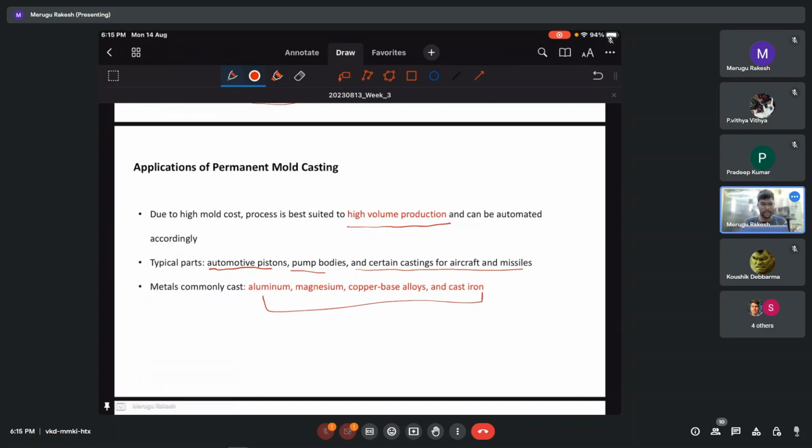So now we come to die casting. In permanent mold casting we are just making the mold, and we are not applying any higher pressure. We are applying a very limited amount of pressure, as you can see here, as we are just pulling the plunger out. But when you say die casting, we generally work around 7 to 350 megapascals.